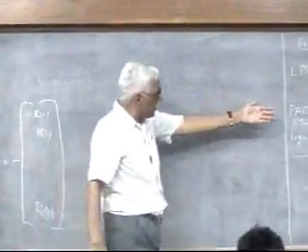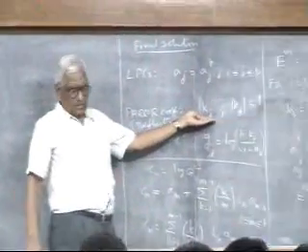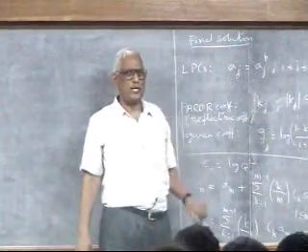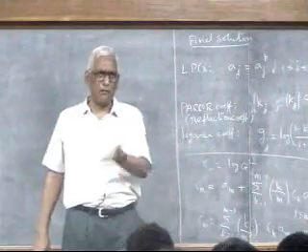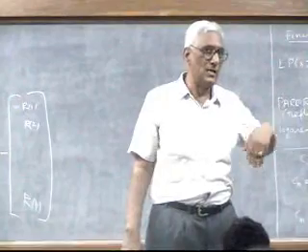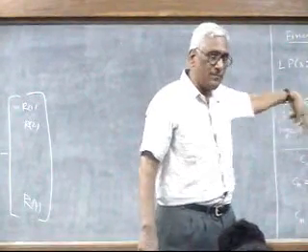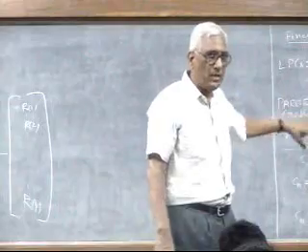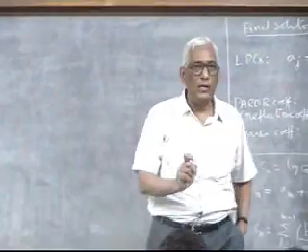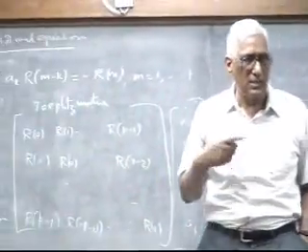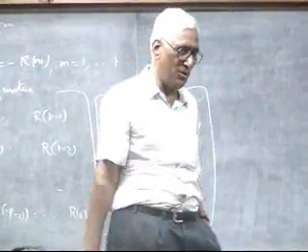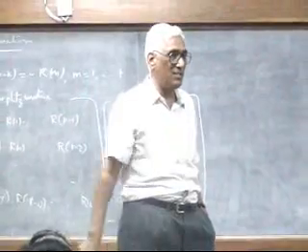My goal here is to show you that the solution gives me, of course, the LPCs. But I don't have to use LPCs. I can also use reflection coefficients to represent my solution. Because the P's and A's are interchangeable, you can solve for the P's from the K's, and vice versa. It's very easy to do. Why this is a PARCOR, you can show by lattice formulation, as a partial autocorrelation, but I don't want to go into that. The point is, the reflection coefficient is important for me.